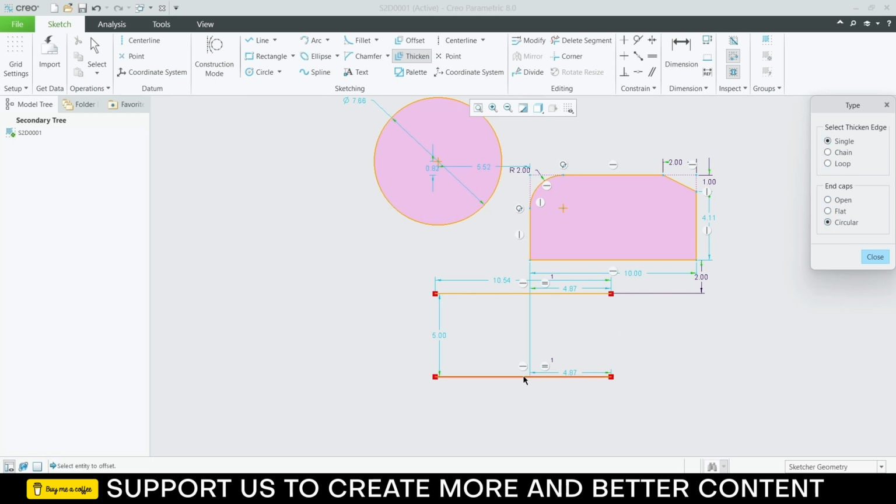Now I will click on this line. It is asking for the thickness. Let's say 2. Click OK. It is asking for the thickness again. 2. Click OK. Notice how it makes it. It takes that previous line as a center line and gives it the thickness. So these two lines are the thickness, and these semicircles are because of the circular command. If I click on flat, it will create a rectangle.